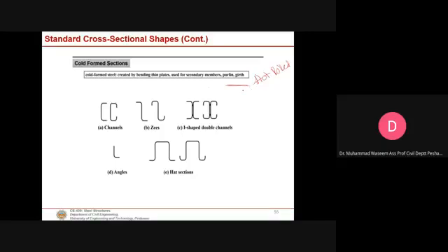Okay, and it is cooled, and you have brought it from the factory. It is placed, say, in the structural engineering or structural testing laboratory, and you want to change its shape. What you do is bending. So this type of shape is produced by bending or molding the shape of the members at room temperature. We call such members cold form members or cold form sections.